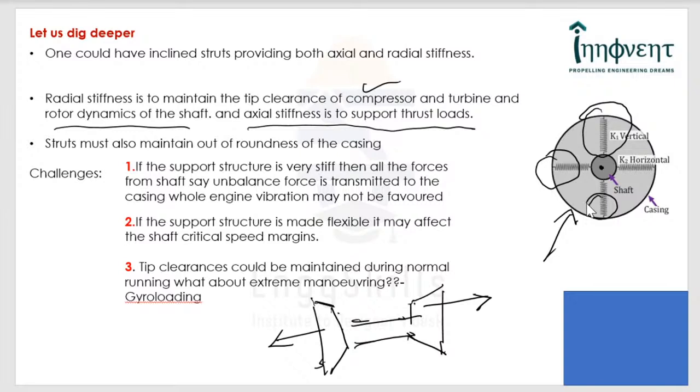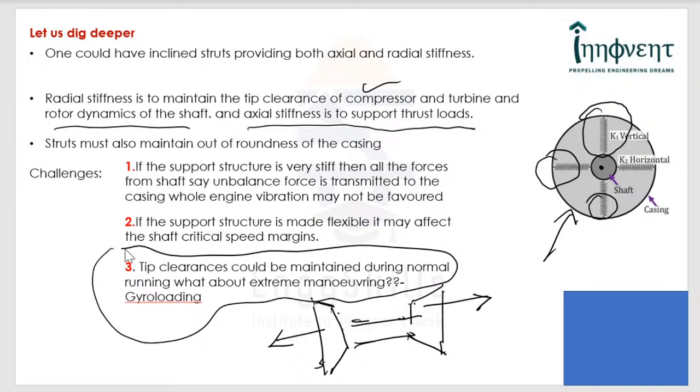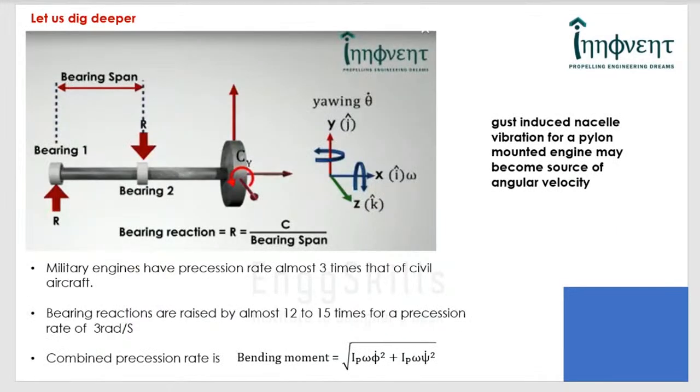Now, what becomes very, very challenging as we proceed further? Now, if you look at a typical gas turbine, there can be a lot of maneuvers, but of course for a civil aircraft, the maneuvers are quite disciplined, and it is far less compared to your military aircraft. But whenever a maneuver happens, it brings about very, very important loads, inertial loads and gyroscopic loads. Now look at a typical situation. When the aircraft is moving absolutely steady, there is no gyroscopic load.